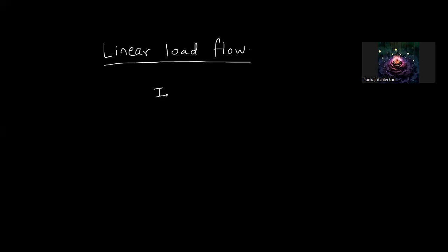So for the network, we represent the bus currents, basically bus injections, and the bus voltages. They are related by a simple linear equation, which is Y bus into V bus. This is a matrix linear equation that represents the network part in the system.